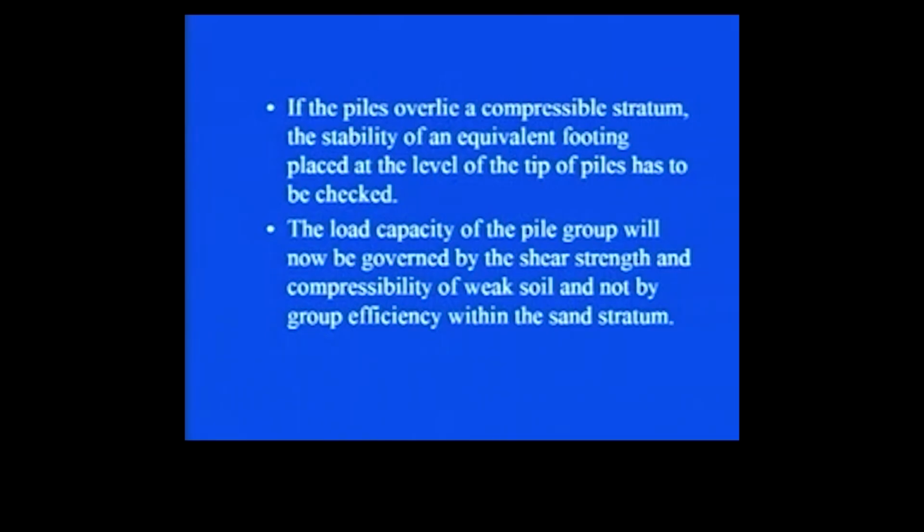The load capacity of the pile group will now be governed by the shear strength and compressibility of the weak soil and not by the group efficiency within the sand stratum. So, in case any compressible stratum or loose sand stratum is present, the load capacity of the pile group will be governed by the properties of that weak soil, not by the group efficiency.